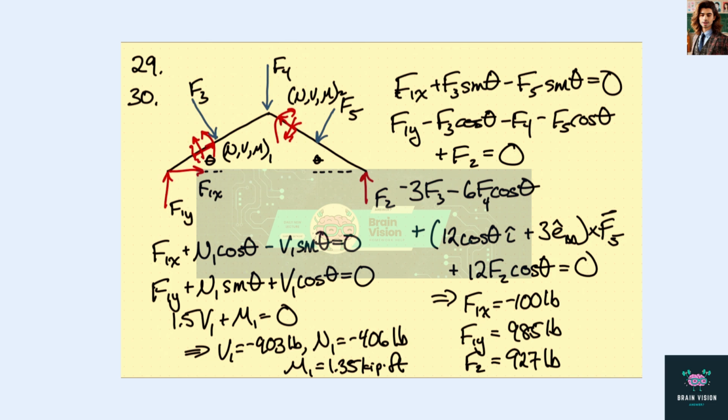So we have this kind of arch structure that's basically a bent beam, and then it makes a 30-degree angle here with the horizontal. It is pinned at this end, and then the roller support at this end, and then we have a load at the peak, and then loads midway along these rising and falling spans that are normal to those spans.